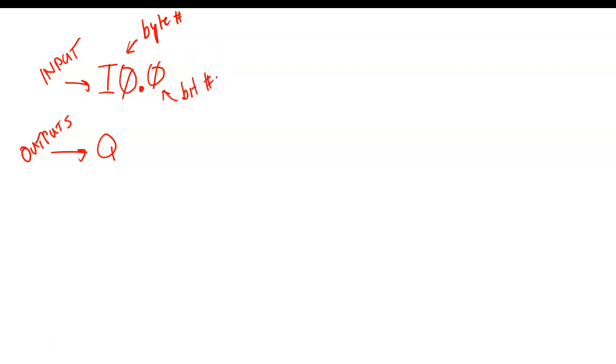That's a byte number. If we wanted to do a whole byte, we would go IB. We go IB, and this would stand for a byte. I'm dealing with a whole byte. Then we put a period, and then we'd put a byte number. So this is basically what you're dealing with. And I like this better because if you wanted to do a whole word, you'd say what? IW, which I really like. And then you put a word number. So the dot just separates what you're dealing with and what you're